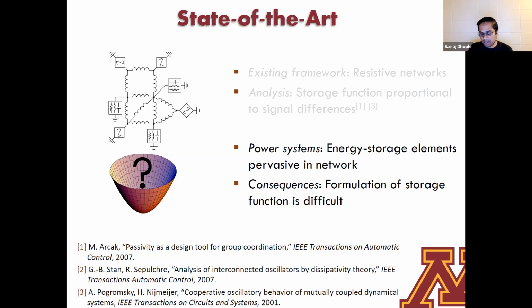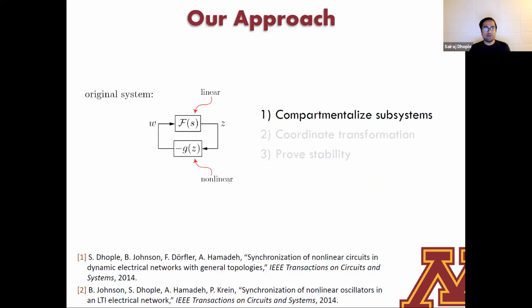So we're not going to do a Lyapunov-based analysis in order to show synchronization and these desirable properties. What we'll do is leverage an L2-based method, and this is really looking at a product of 2 gains of these systems. There are 2 types of systems here. There is a linear collection of all the oscillator linear components as well as the network linear components, and I'm combining all of that and calling it a giant transfer function matrix.